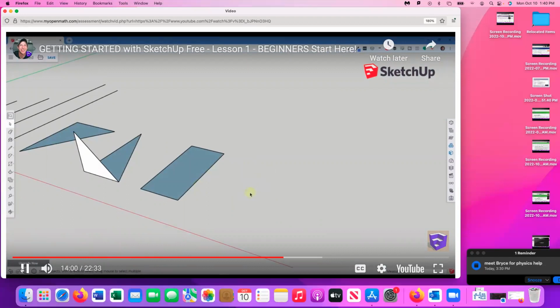And so now I want to talk just a bit about these different colors that are showing up when we have tools active. So let's say, for example, that we activate the line tool by tapping the L key again. And you can see how if I start moving my mouse over different edges, I start getting these little different shapes and colors, and dotted lines start showing up, and all those different things. Well, what those are is a part of SketchUp's inference engine. And SketchUp's inference engine is where SketchUp tries to figure out where you want to draw different things. So it kind of guesses where you want to draw, and it also gives you little tips.